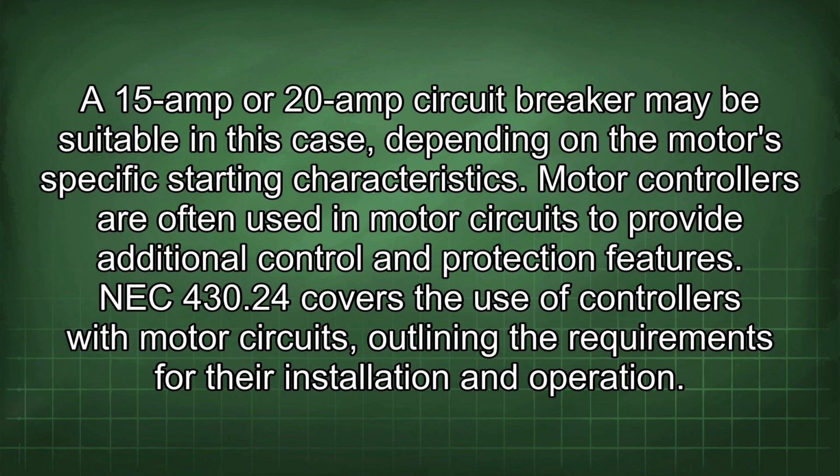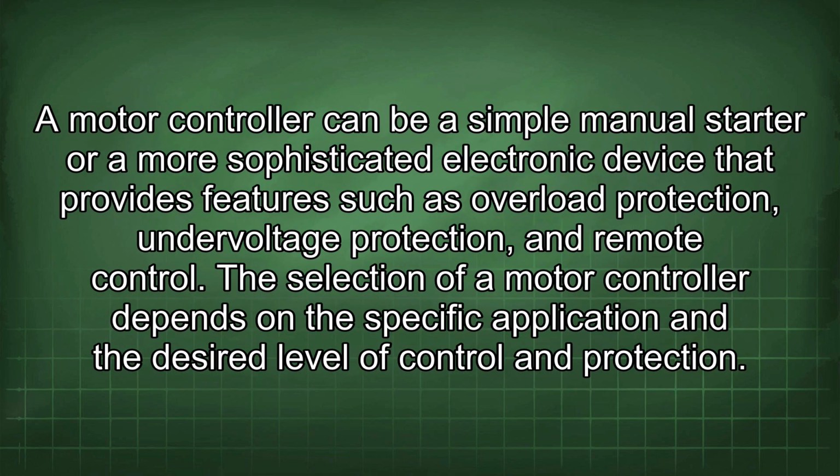NEC 430.24 covers the use of controllers with motor circuits, outlining the requirements for their installation and operation. A motor controller can be a simple manual starter or a more sophisticated electronic device that provides features such as overload protection, undervoltage protection, and remote control.